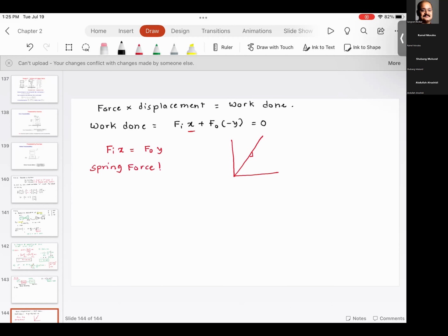But what we have is damping. So if you look at the problem, the force is given as C (V2 minus V1) squared. And to account for the direction of damping, I would use the sign function, which is sign(V2 minus V1).